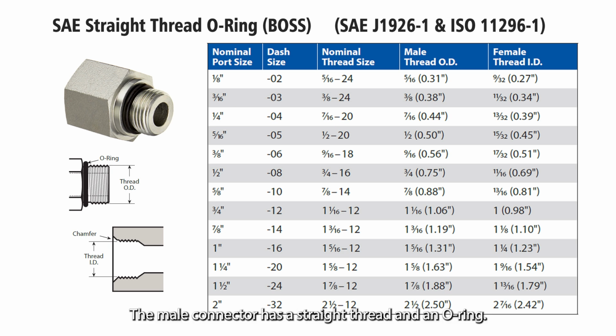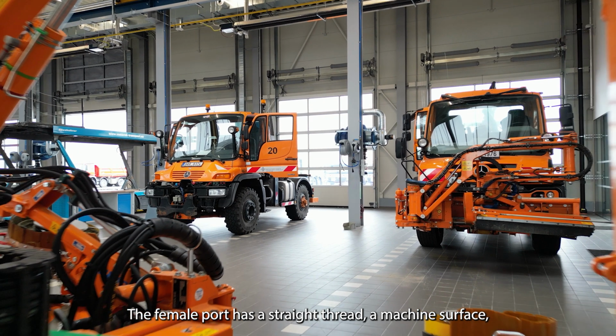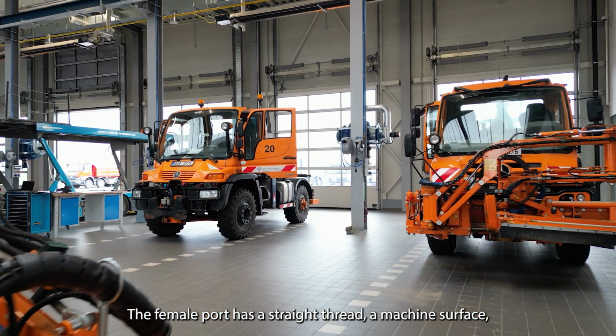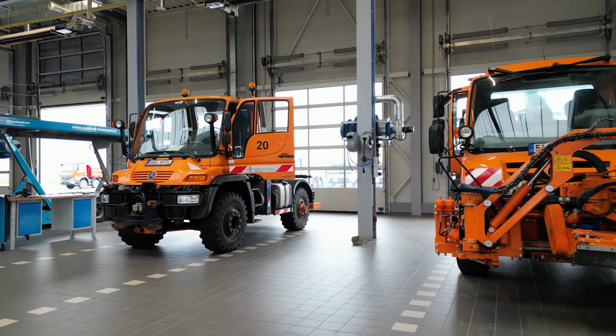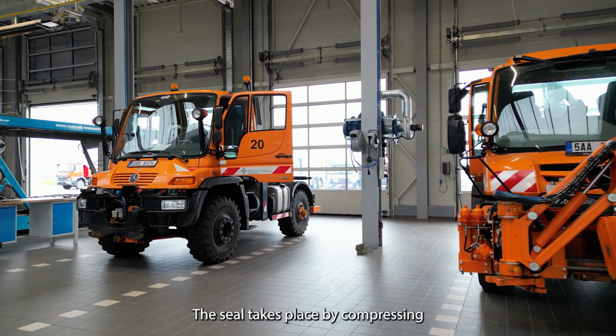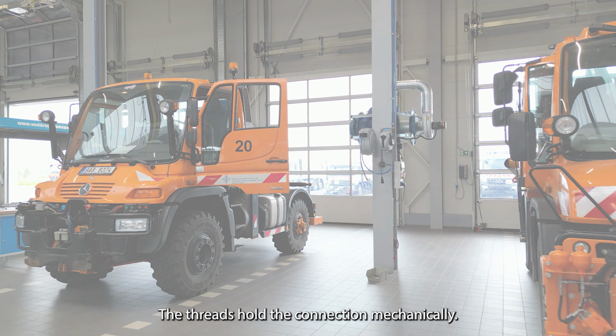The male connector has a straight thread and an O-ring. The female port has a straight thread, a machined surface, minimal spot face, and a chamfer to accept the O-ring. The seal takes place by compressing the O-ring into the chamfer. The threads hold the connection mechanically.